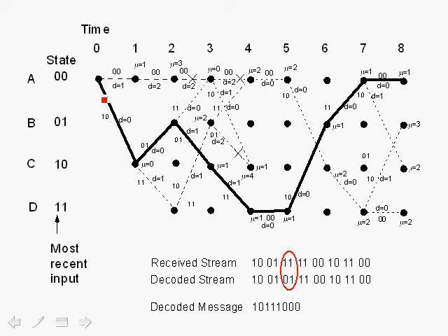So imagine a matrix with 64 rows, and the number of columns is associated with the constraint length. Now, the number of columns that you store is typically 5 times the constraint size. This diagram shows a traceback depth of up to 8 clock cycles.